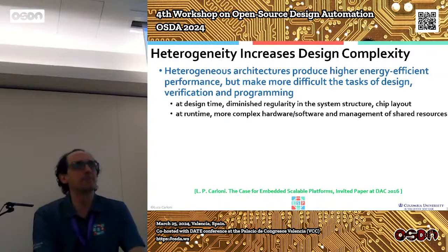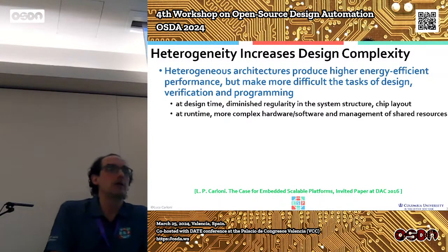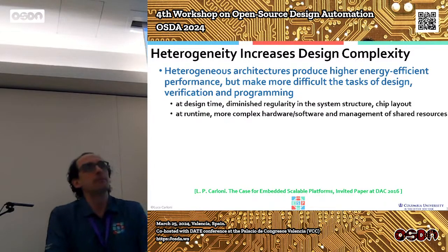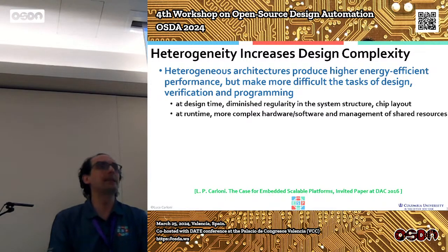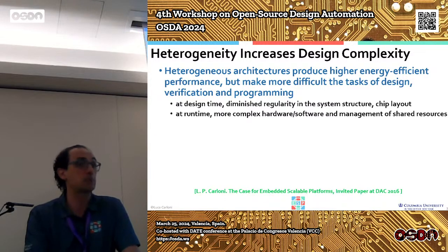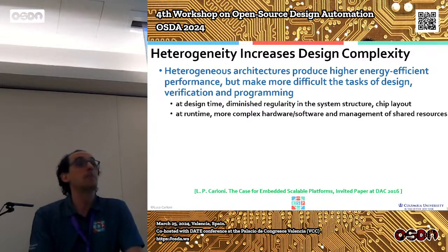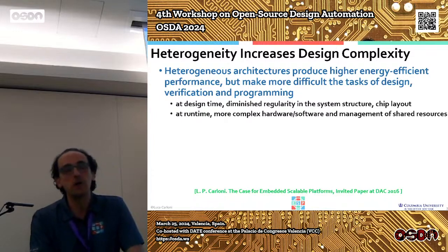Now, I don't have the time to explain why heterogeneous computing has emerged. Essentially, there are all those technology trends, particularly the slowdown of Moore's law, and particularly the end of Dennard scaling, that make the need of using transistors to create specialized hardware compared to a general purpose CPU. And fixed function accelerators are even more specialized. Why? Because they provide better performance and energy efficiency for a key computational task compared to executing things in software.